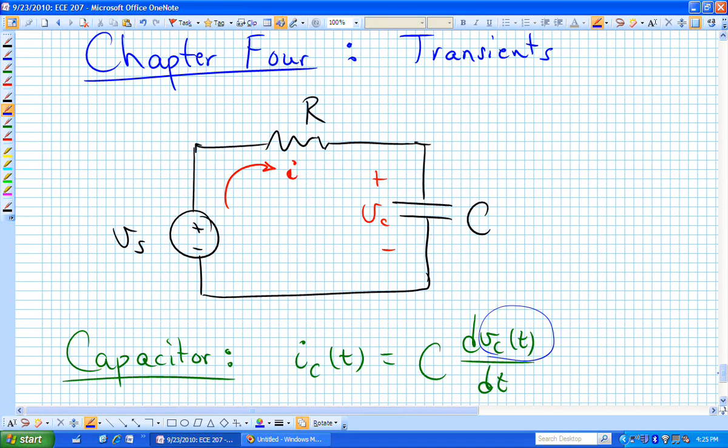If you had a circuit that contained four capacitors interconnected, you would be looking at a fourth-order system. For Chapter 4, we're only dealing with one, or an equivalent. So we only have first-order differential equations in the first part of Chapter 4. We will actually start putting resistors or inductors and capacitors in a circuit. There's two energy storage devices. Now we have a second-order differential equation.